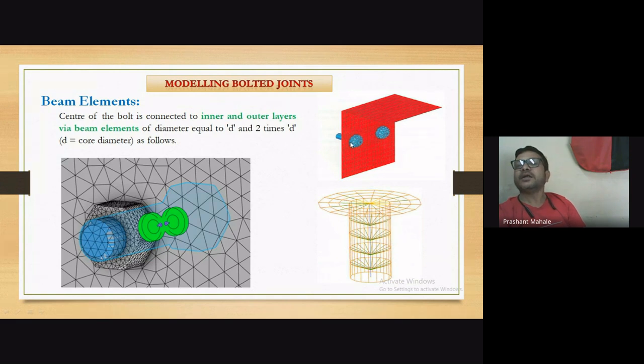Here you can see that where bolting is done, the meshing nearby is somewhat refined, and on the bottom side also, because we have stress concentration near the bolt holes. In this way, the bolted joints are going to be modeled and represented, and these are the considerations we need to keep in mind when going for analysis using bolted joints and welded joints.